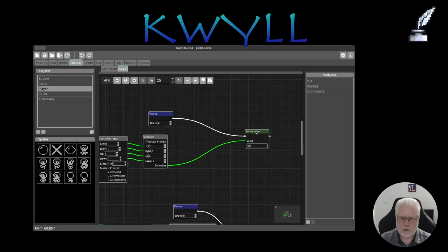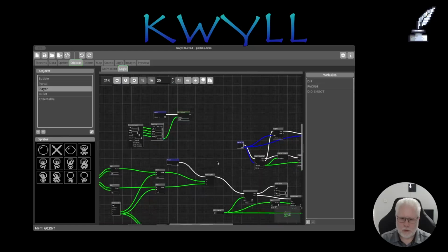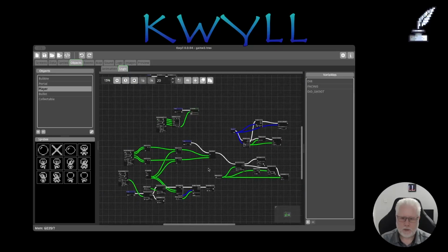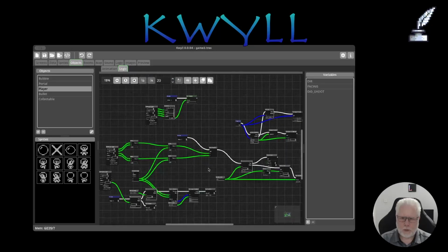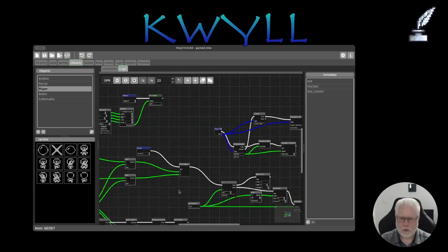So now if you do anything in the logic editor, you've got undo and redo. That applies to connecting, disconnecting, changing properties, adding, and deleting nodes. The only thing it won't do is if you delete a node, it will delete all of the connections. If you undo that, because of the nature of the undo system at this point in time, it will bring the node back, but it won't refix the connections. So that's going to be a manual fix up. If I can work out a way of doing that for 1.0, I might. If not, it might have to wait until 2 or the next release.